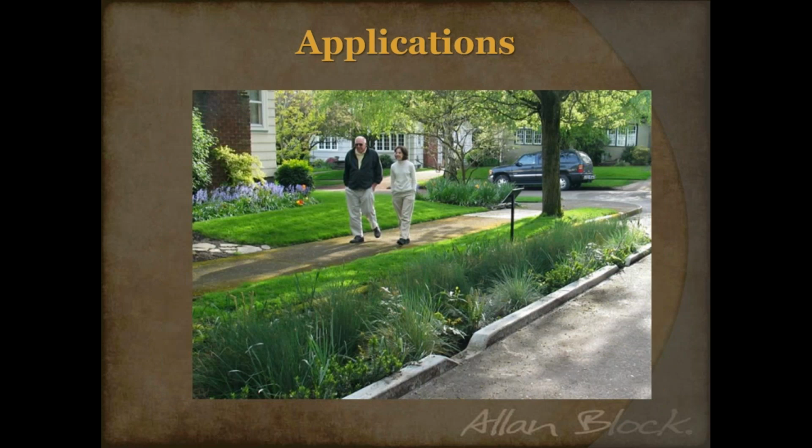Here, a little bit more of a bioretention swale. Again, somebody might walk right past this and not even realize the importance of it, but you can see you've got inlets at designated points for that parking lot, and that's going to be captured by that bioretention, ultimately going into some type of a collection system, maybe down into your subsurface or to that outlet pipe, but at a much cleaner and slower rate.